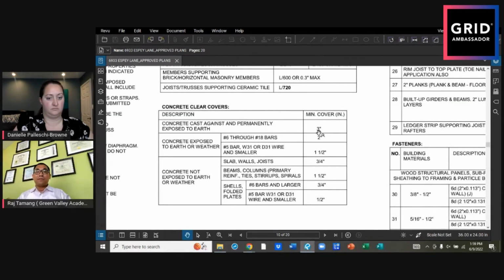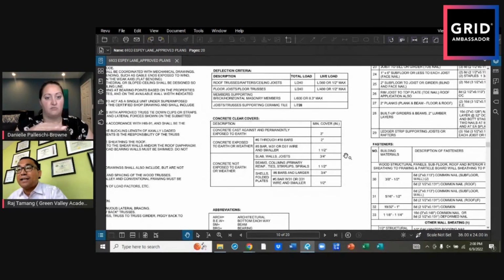So how they do it, sometimes I see they put pieces of rebar, or sometimes they have a chair. For residential construction, I have not seen it. Usually contractors just use those bigger size aggregates to hold it up in place. But in commercial projects, it has to be perfectly done. You can buy metal chairs with exactly 3 inch, 1 inch, 2 inch height where the rebar can sit, so that you can maintain that gap or clearance correctly. It's called concrete cover. Because if you don't do it correctly, you don't get the strength.